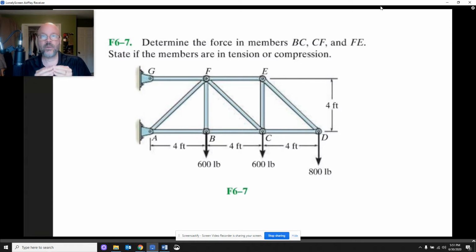That's where we go to every specific pin and decide we need a free body diagram, and that pin has to be in equilibrium. So we look at everything that's pushing and pulling on that pin, and we go from pin to pin to pin and try to figure out what's happening there. And we work out every single joint. And if you have something complicated, you're going to have a lot of joints to do.